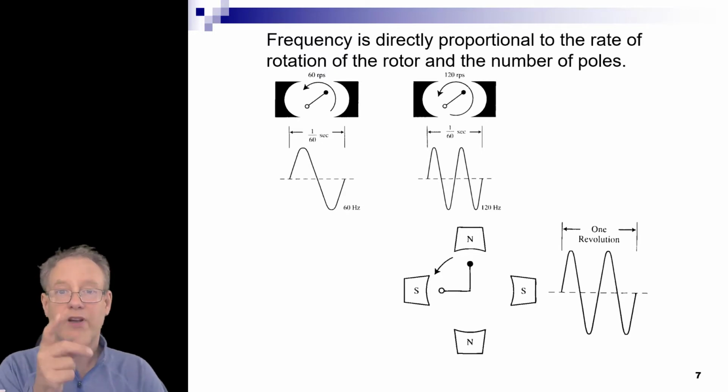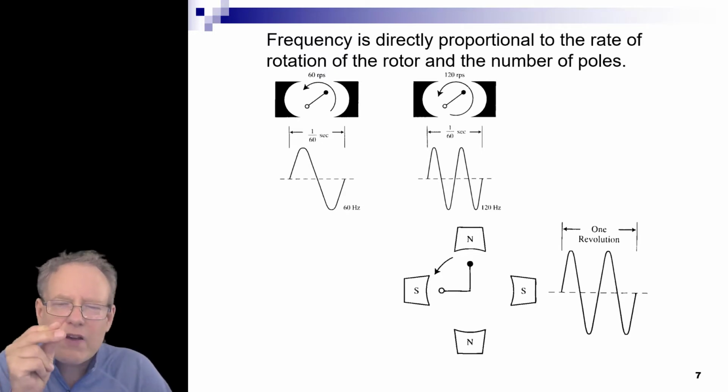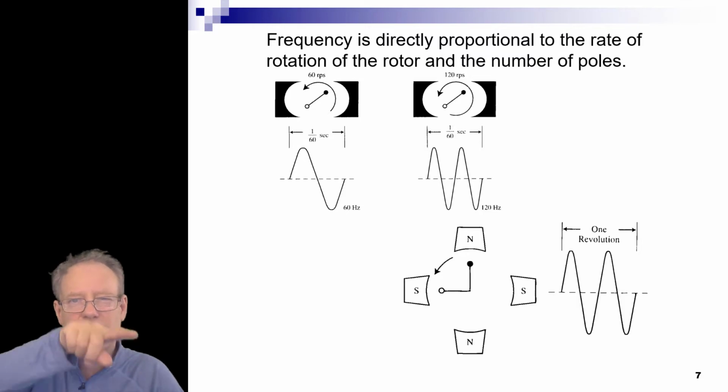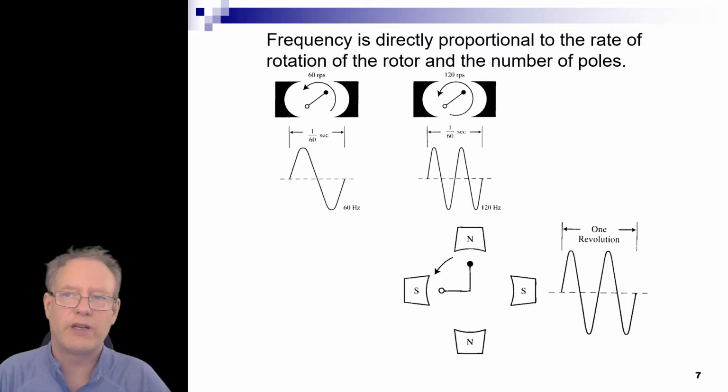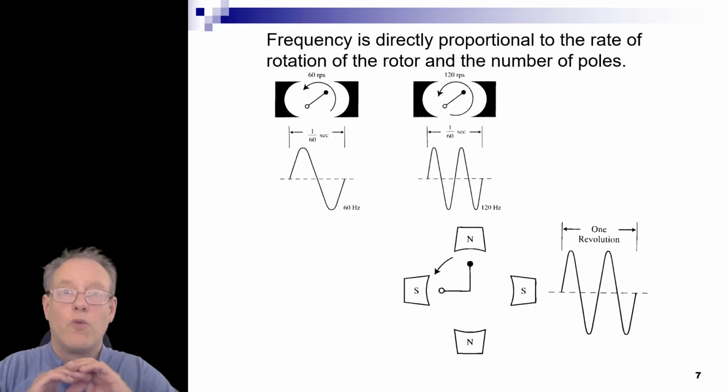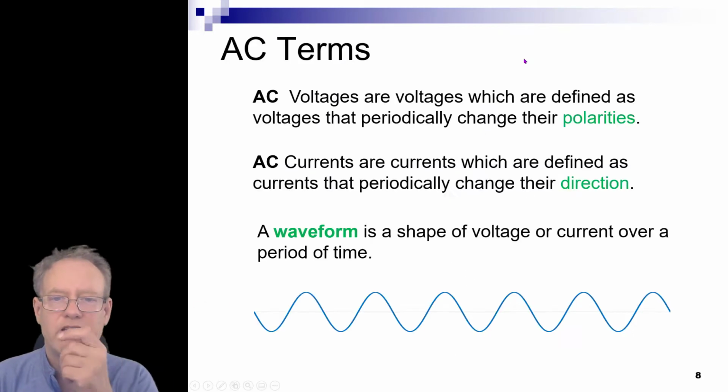By the way, they're governed, so they move very specifically, exactly at a certain speed. They can't speed up or slow down, or else we'd get some frequency that wasn't 60 hertz, because 60 hertz is what we run on our grid. Okay, let's continue on here.